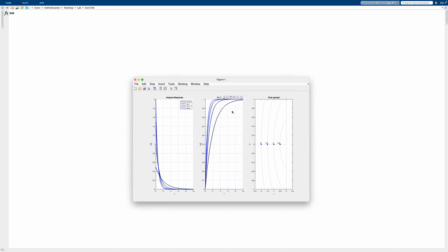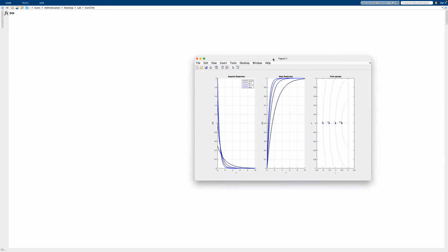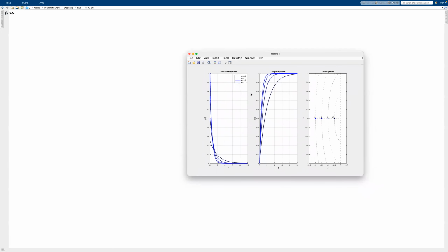Now, we call the point where we enter the steady state, the time instance, the settling time of a system. So basically, we have some percentages. Since this is a first order system, and we know the model of it, it's quite easy to calculate and obtain at which time instance we get to the 5% band or 2% band, which we never leave. If that's the case, we just assume that the system is at steady state. It is at rest.